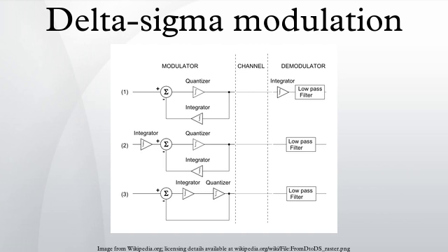A very accurate transmission system with constant sampling rate may be formed using the full arrangement shown here by transmitting the samples from the buffer protected with redundancy error correction. In this case there will be a trade-off between bandwidth and n, the size of the buffer. The signal recovery system will require redundancy error checking, digital to analog conversion, and sample and hold circuitry. A possible further enhancement is to include some form of slope regeneration. This amounts to PCM with digitization performed by a sigma delta ADC.